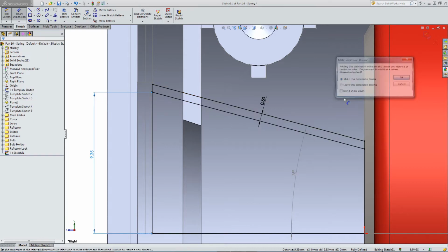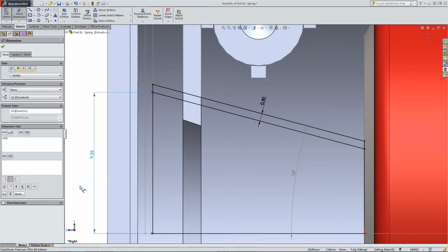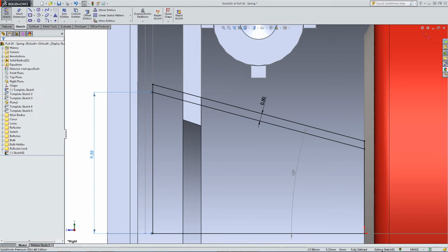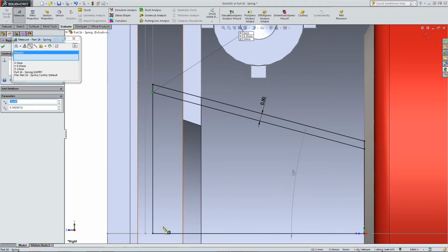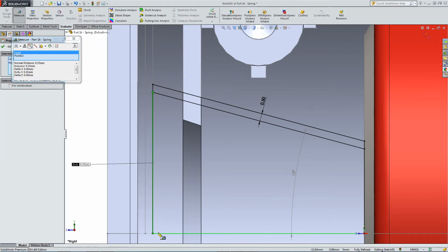And just setting up these sketches. These sketches are not driving the geometry, they're just to show the dimensions. And sometimes it's good to remind yourself of the dimensions, so when you come to add your spiral for the spring, you've got your references right.